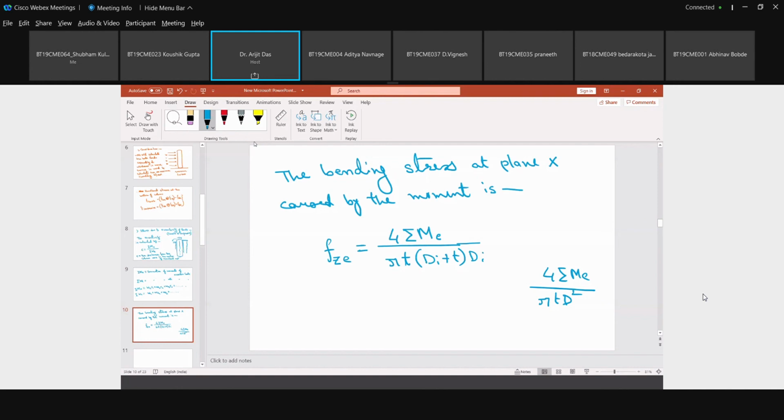Anyway, so these are the effects of the seismic load on a self-supported tall column, and the effects of the eccentric loads, that is different attachments on the tall column. So we now already know the different loads or the different stresses induced in a column. First, we know the stress induced by the internal pressure. Two types of stresses are generated. One is the axial and second is the circumferential.